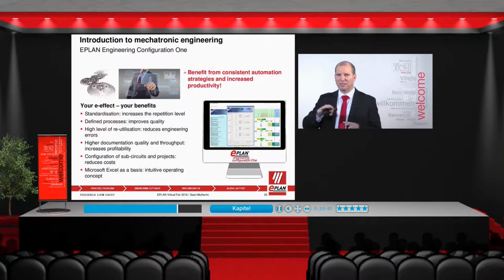This is your first step to complete automation, meaning that you can use a front end such as Excel to capture data. You map that data to your macros, which are your circuits or your partial circuits, and you can use that to auto-generate your fluid, your electric, and some of your ProPanel layouts automatically.